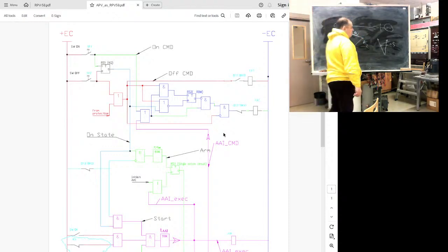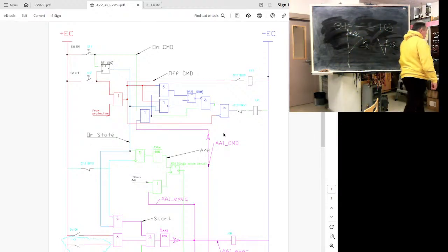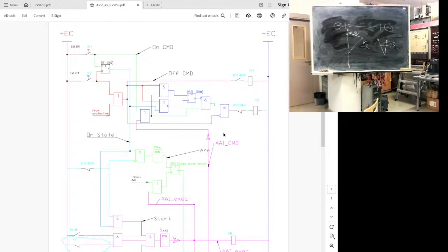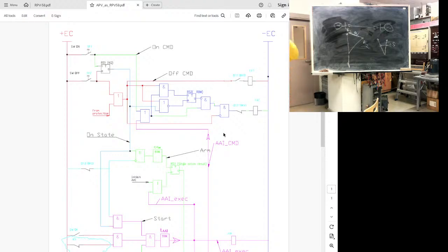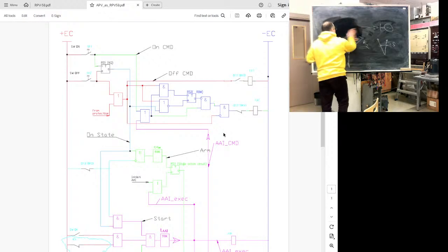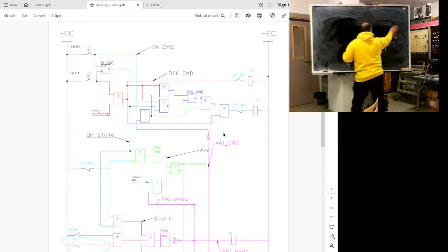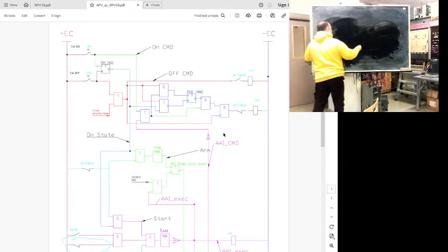When we are dealing with a situation where power can come from both sides, we need to perform a synchronicity check, or synchro check. The simplest way of synchro check, in early days, electromechanical voltage difference relays were used. The idea.